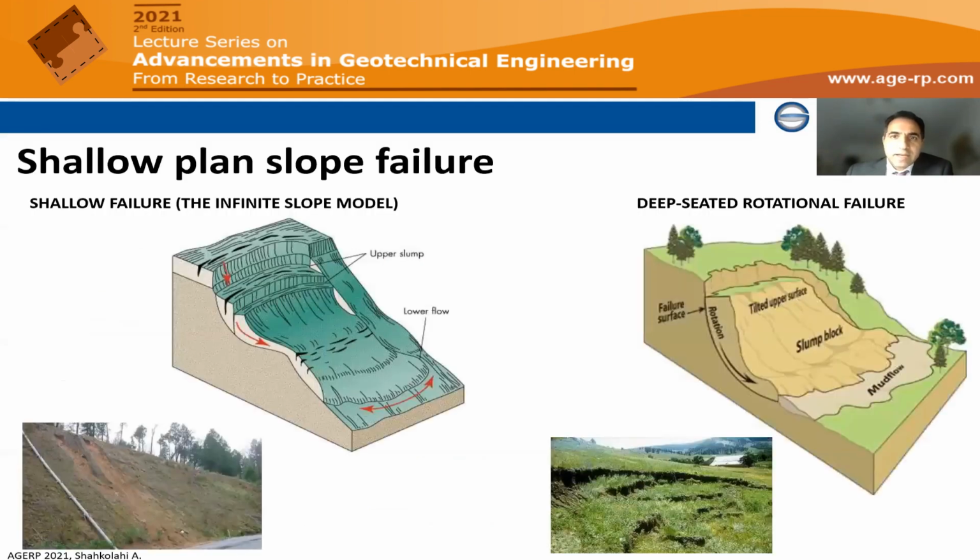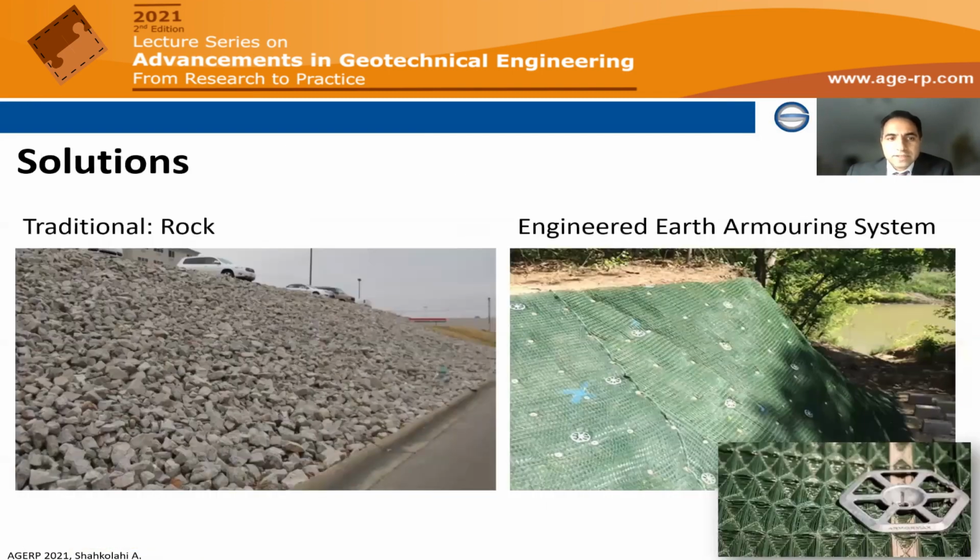Another application is when we have erosion control, but also some superficial stability issues. So, it's a typo, slope failure. So we have shallow failure at the surface. It's not global stability. It is just superficial stability, let's say up to 3 meters deep. These are the situations that we can also control by these systems. What we do with a traditional solution is replace it with rock, and hopefully this rock will protect against the erosion and everything.